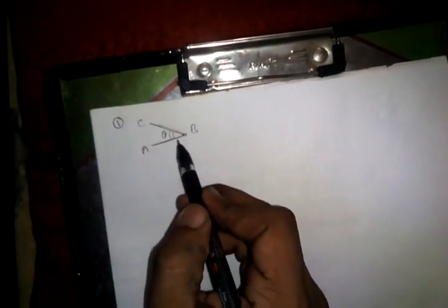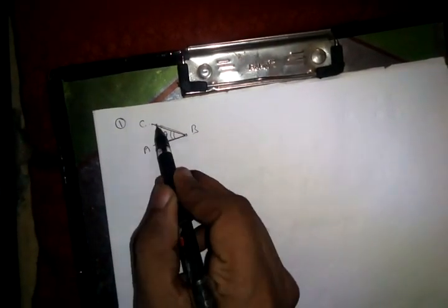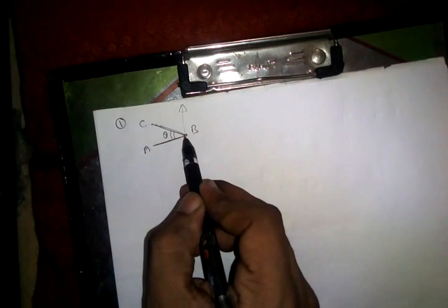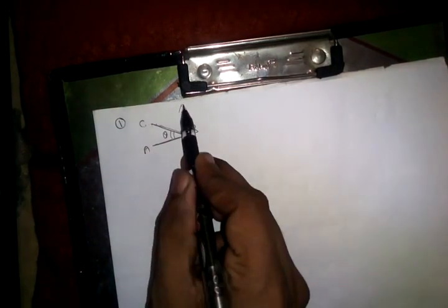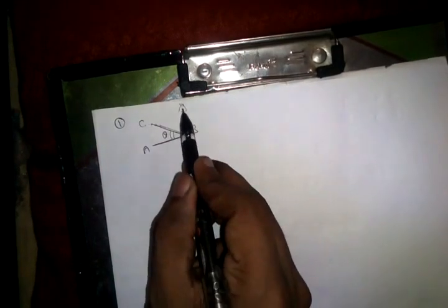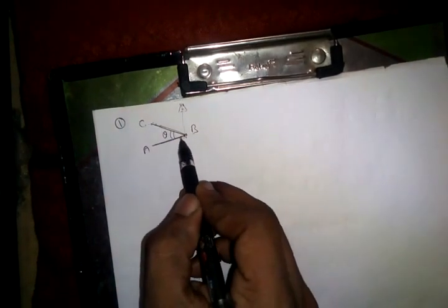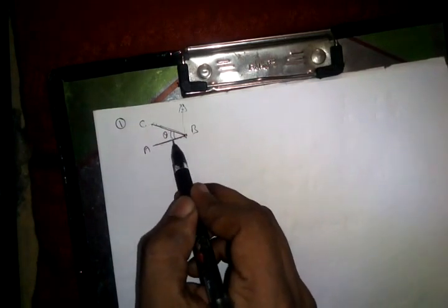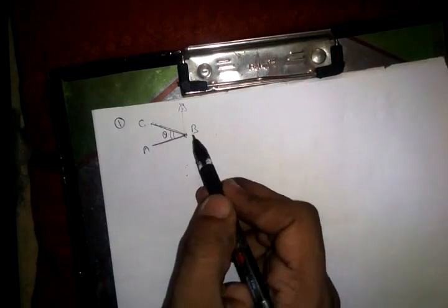So in this case forces FBA and FBC will be 0. Why? Because if I write the equation, this is FBC cos theta, and this is FBC sin theta, so FBC sin theta equals 0 because up equals down, up is FBC sin theta and down is 0, so FBC is 0. And once FBC is 0, FAB will also be 0 because FAB plus FBC cos theta equals 0 and this is 0, right? So in these two members the force will be 0.